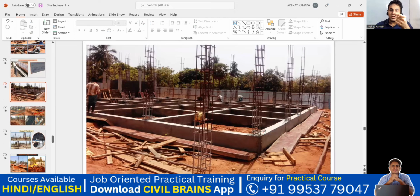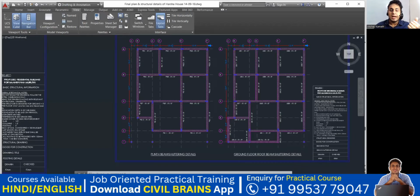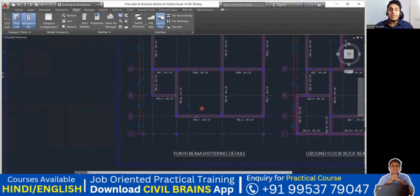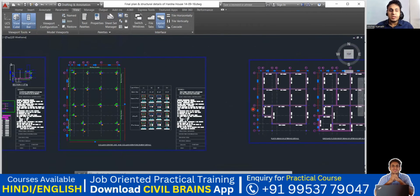Now, what is the width of this? What is the depth of this? That I don't know. For that, I need to go back to the drawing. What is written here? Plinth beam shuttering details. That means the shuttering you're supposed to put is given here. Now we'll try to see here. So you can see the same thing here.